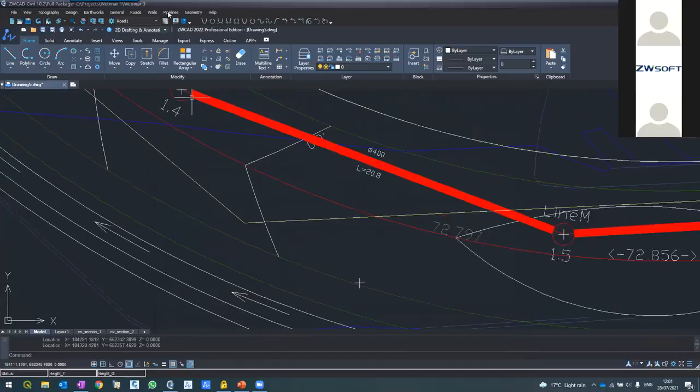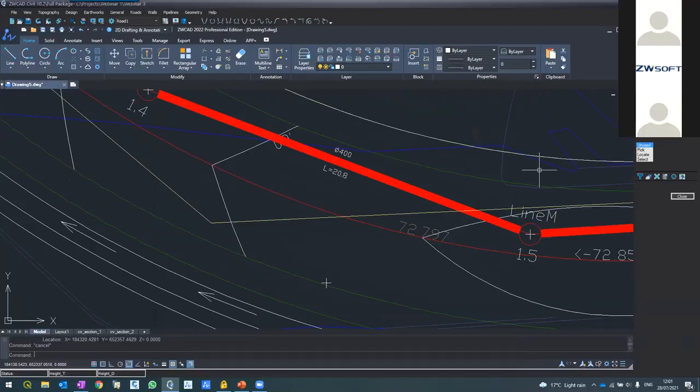So I'll tell the software, go into the crossings. Crossings are the crossing infrastructure. Go to this layer, we call it, and find all the lines which sit in this layer, because it can have many. So the software automatically identifies 4 points of crossing with electricity.